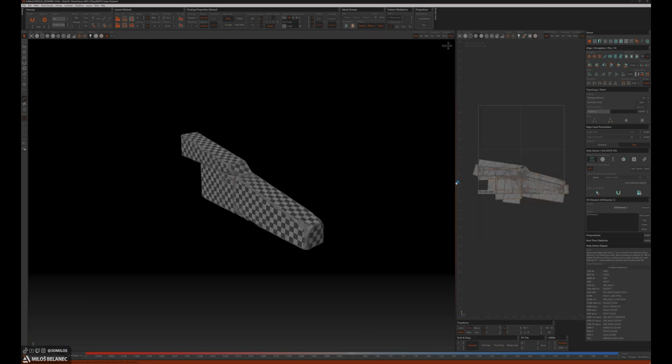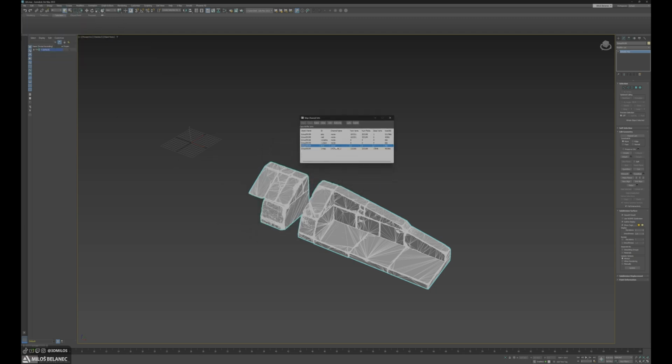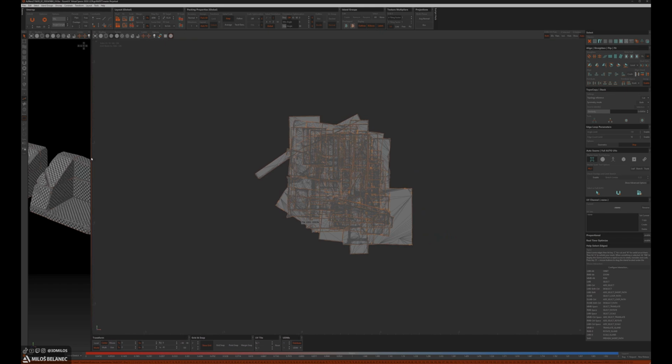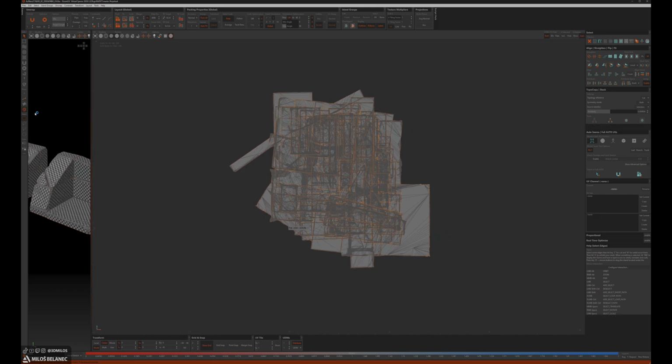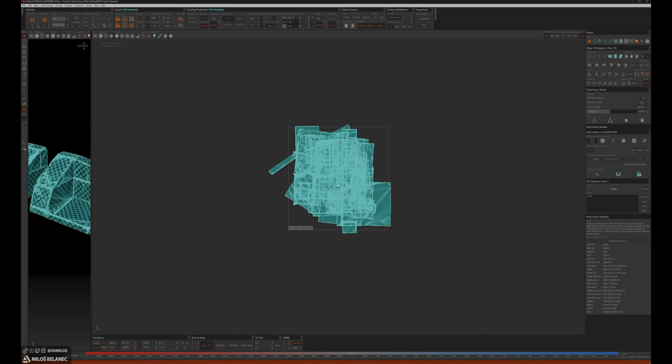And a quick tip, if you have a problem with saving the UVs, check if you don't have multiple channels or a channel name in the UVs. This tool is for 3ds Max, probably something similar exists for all 3D tools. Okay, everything is done. Now we need to pack it. Just check if your texel density is the same for all islands. Set spacing and maybe rotation in the packing, and the model is ready for Substance Painter.